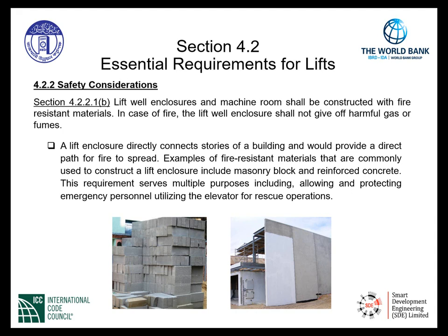That's why we have this section here to be made of fire-resistant materials when it comes to lift well enclosures and machine rooms. Examples of fire-resistant materials that are commonly used to construct a lift enclosure include masonry block and reinforced concrete. This requirement serves multiple purposes, including allowing and protecting emergency personnel utilizing the elevator for rescue operations.